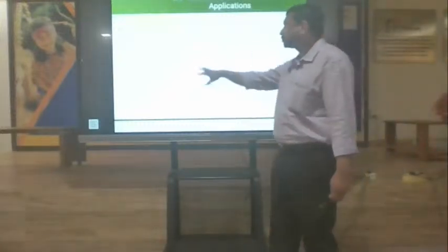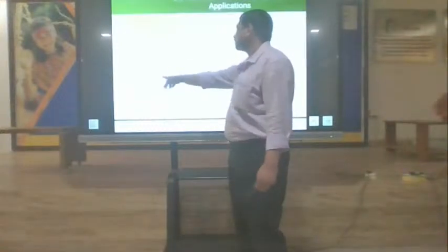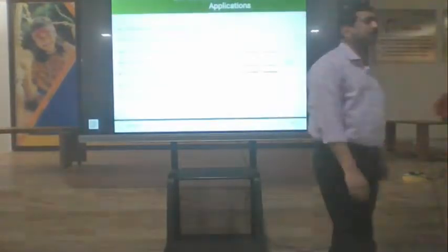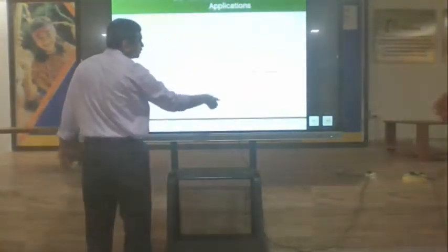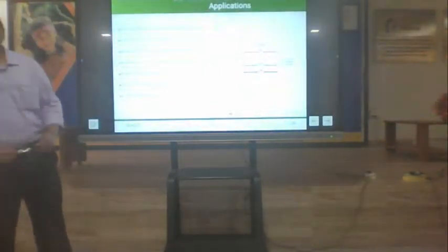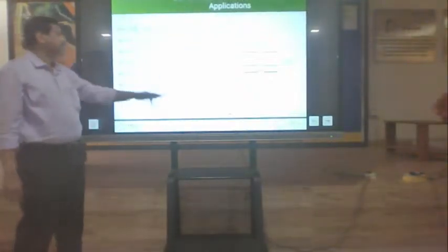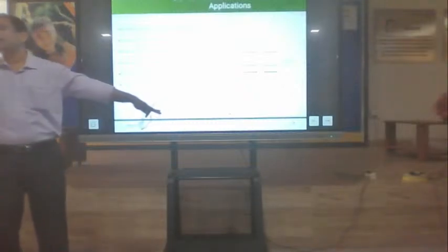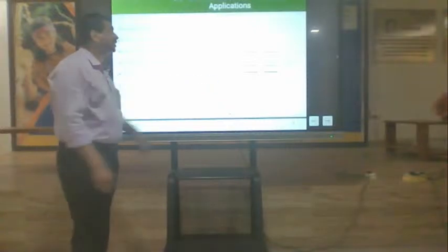So generally a rooftop solar is like this. These are all the panels. The symbol of the solar panel is that. Here the solar inverter is this. These are all the inputs of that DC converter. So we have connected how many? Around 15 panels in series. And how many like that? 8 panels in parallel, and that is getting connected to the